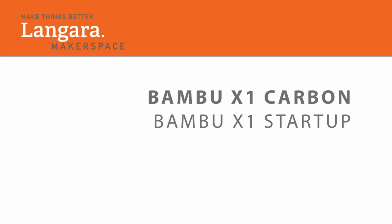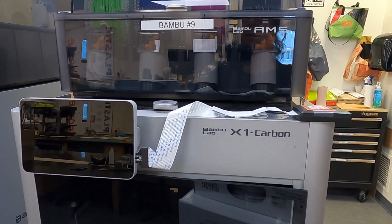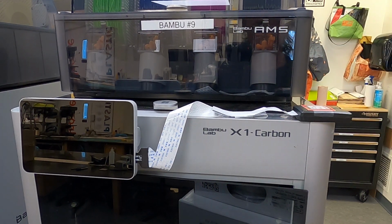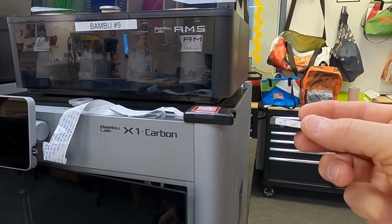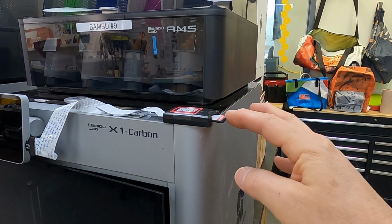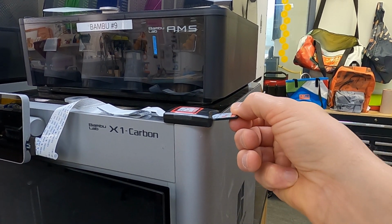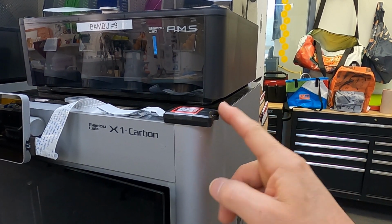Okay, we're now going to go to the Bambu printer, and you want to go to the one that you've signed up for. The number's on the AMS material loader. This is Bambu 9. And now we want to take our SD card. The SD holder is on the top, and you want the label up. You want to gently push it in and let it pop back, and it's going to click. And it should be just under flush. Again, I'll push it in, just gently push it in, it'll pop back and click. And just under flush.